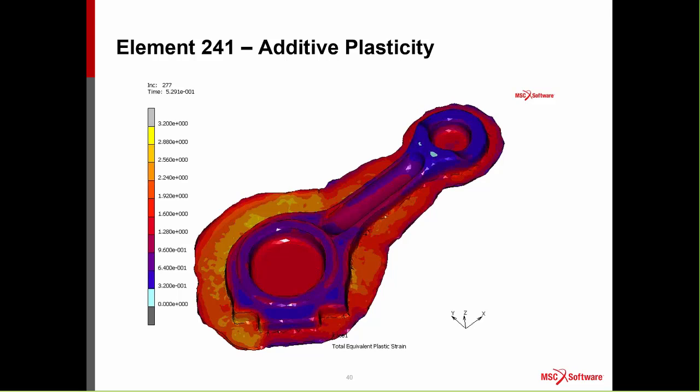You can use both the multiplicative plasticity, the FEFP formulation, or you can use the additive formulation. But the element is a little bit expensive. And what we recommend is that you try to use the iterative solver, because the element generates a larger bandwidth than the conventional types of elements.